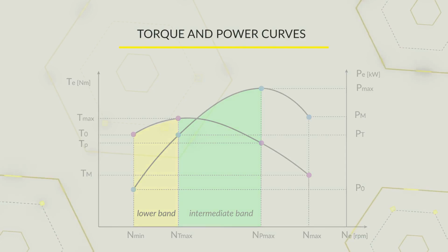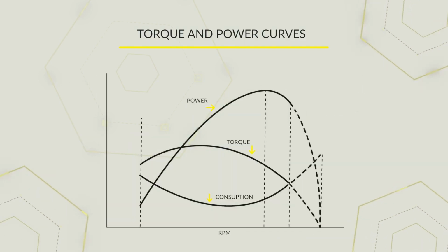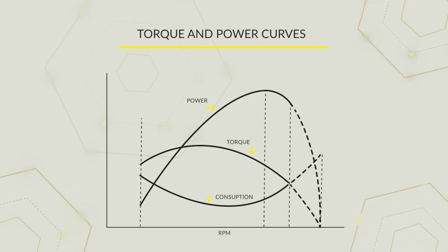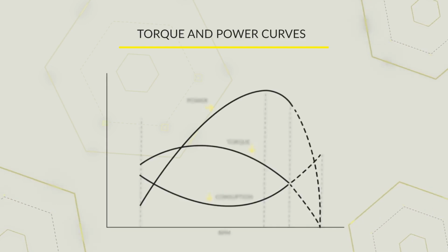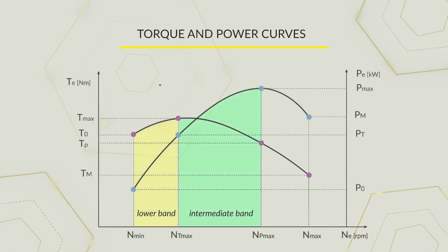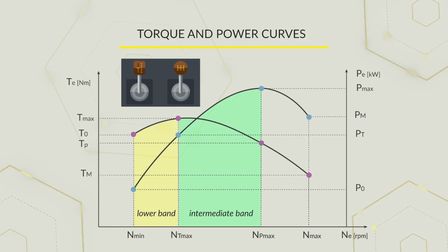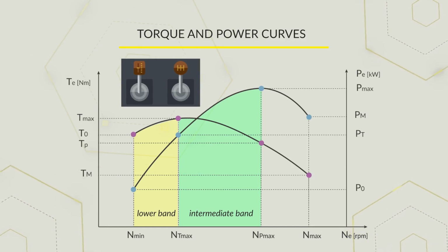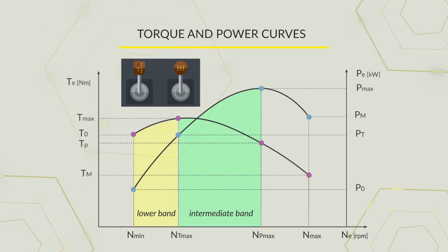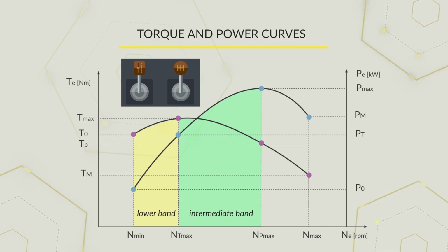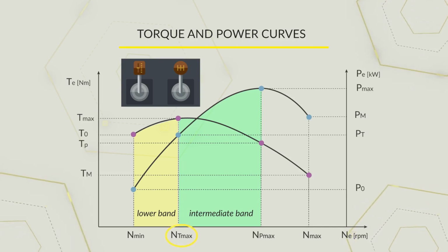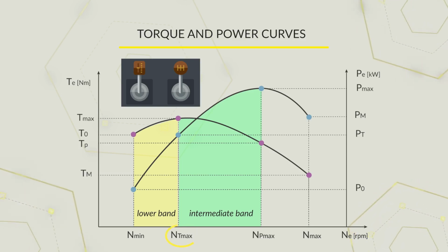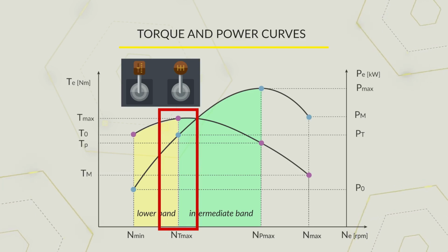Let's analyze a consumption chart. The extreme acceleration phase does not represent the actual driving condition of a vehicle, but only describes the most favorable gear shifting condition. Today, manufacturers plan to equip vehicles with manual or automatic gearboxes with a number of gears ranging from a minimum of 5 to a maximum of 10, where the transmission ratio allows you to shift up to a slightly higher RPM at the maximum of torque without drastically reducing the RPMs or, in any case, remaining close to the border between the low and intermediate ranges.